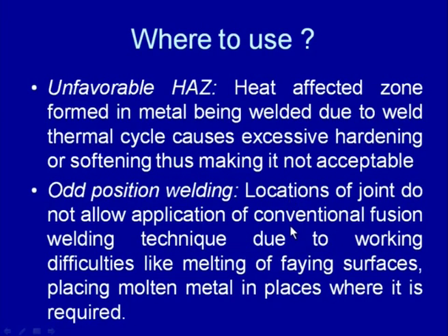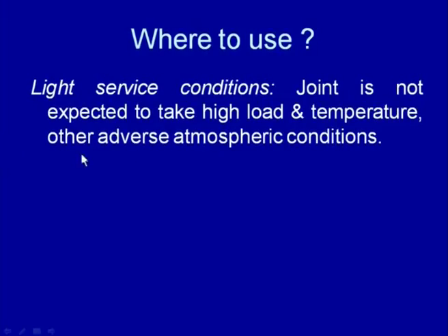the components to be joined and thereafter placing the filler material in the location between the components to be joined, and then on melting of this filler material it automatically gets distributed between the components to be joined by the capillary action. So, under odd positions also this brazing, soldering and braze welding can be used. However, braze welding is slightly different from brazing and soldering, about that we will be talking in detail.